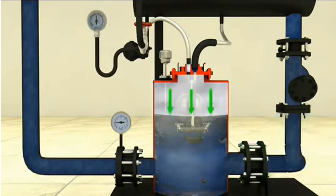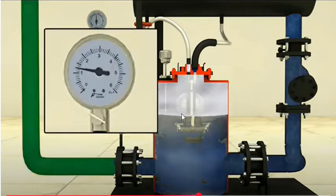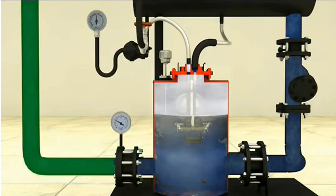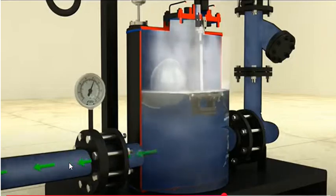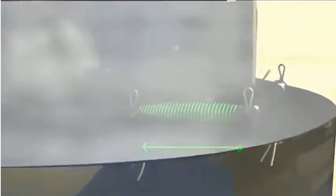Steam flow increases the pressure inside the pump chamber, and once the pressure gets higher than the back pressure of the condensate discharge line, it opens and transfers the condensate to the feed water tank.